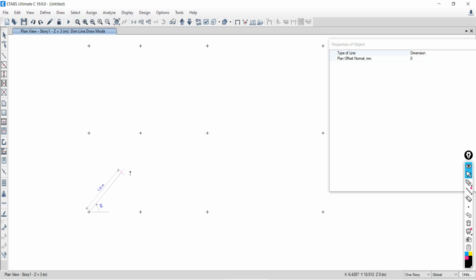And this is the first point. Freely move to the point at which you want to see the distance from the base. So it is 4.6, but my intention is to check the distance only. So what you need to do, the command is there. To turn off this command, right click on your mouse. This will vanish, but the command is active.